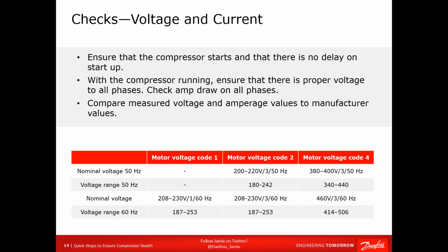So what do you want to check? Well, observe the compressor if it's operating. When you're there, see if it starts. We already talked about starting with the start capacitor. There should be no delay. If it's a three-phase compressor and there's a delay, you have issues somewhere with your voltage. Usually 90% of the time, there's a problem there where you don't have enough power to overcome the pressure differential.